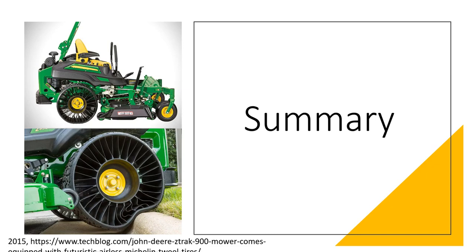However, the airless tires are much better than the pneumatic tires because of the environmental reasons, the price, and performance. Based on the study that was done earlier in the slides, it showed the best design of the spoke structure should be the diamond design made of polyethylene terephthalate. This would produce the smallest amount of deformation, so that's what should be used to produce the airless tire.